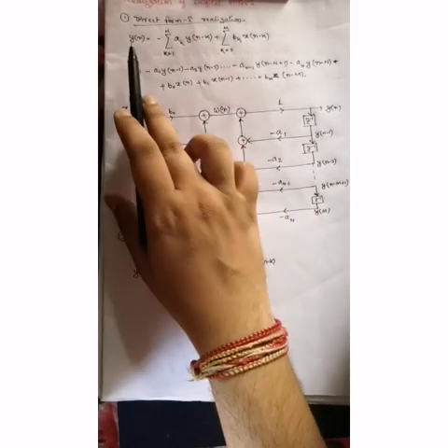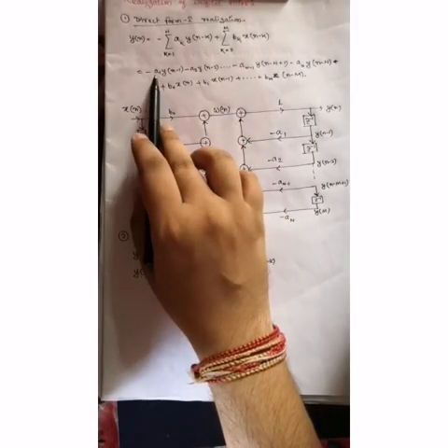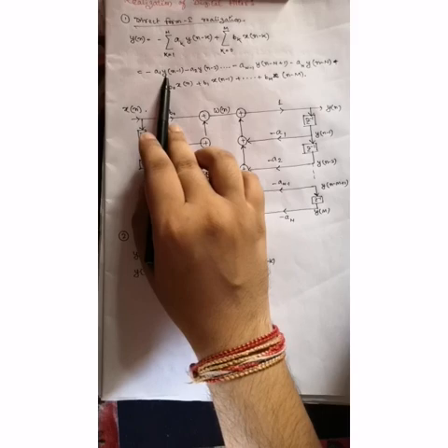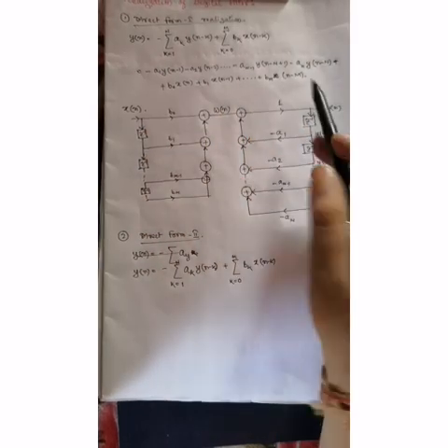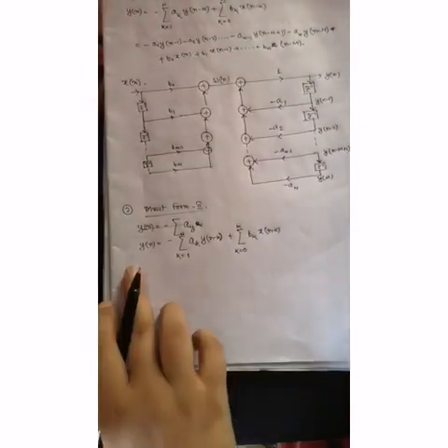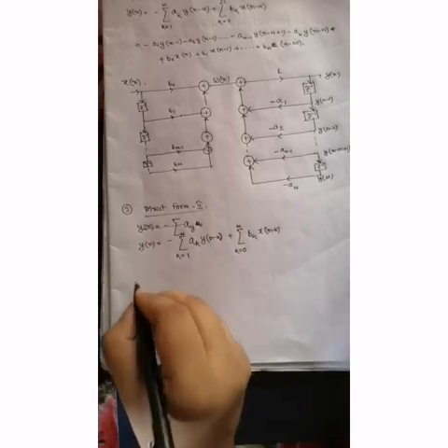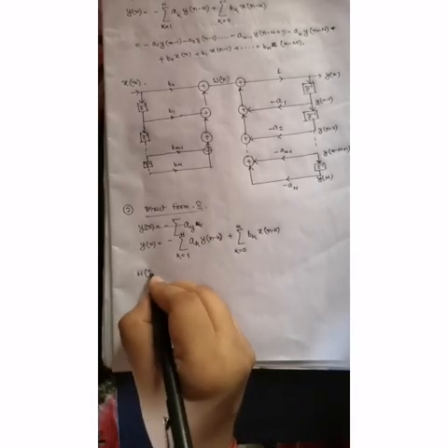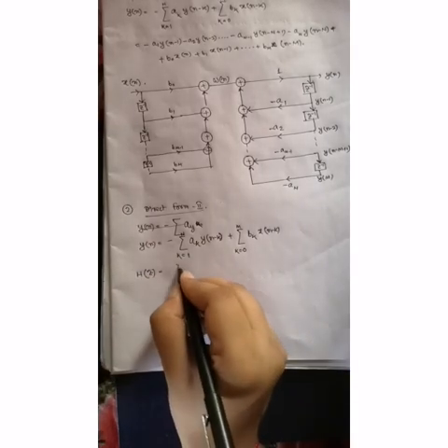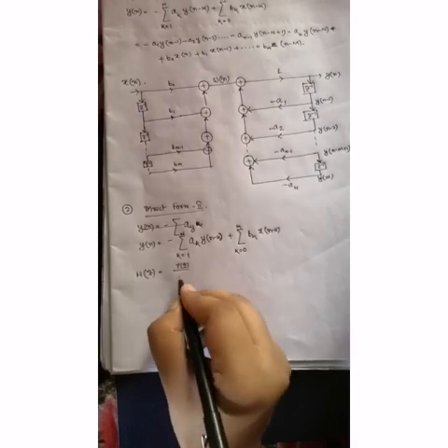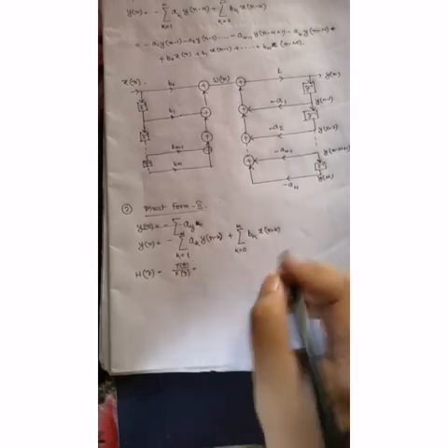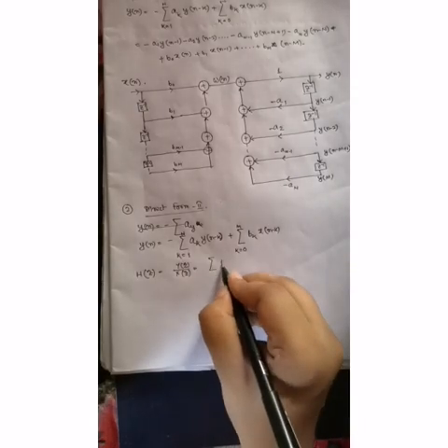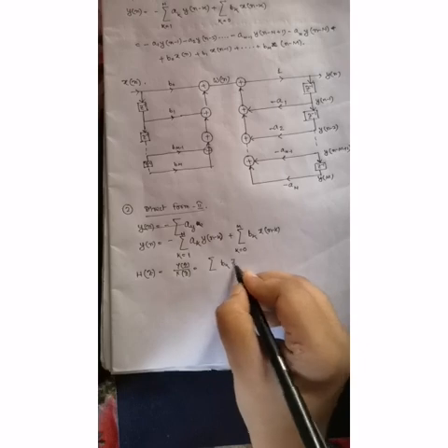That means this yn equals the coefficient of a and y plus this x and b part, we can change it with the wn or omega n. So here this is the yn value, so you have to find the transfer function Hz, that becomes Yz by Xz, that means output by input in z domain.